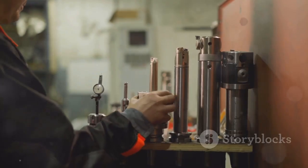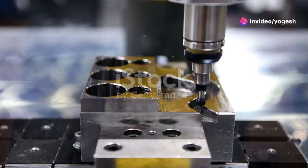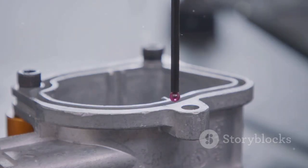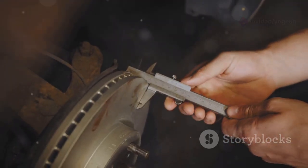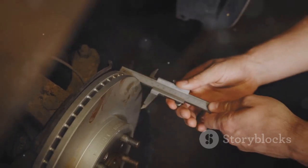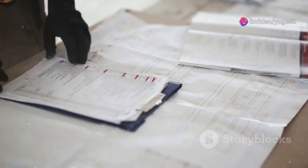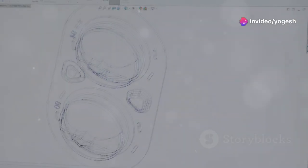Once a part with a spline is made, how do we check it's right? Not with a ruler. Quality control uses tools like coordinate measuring machines, or CMMs. A CMM touches the part at many points, recording their coordinates. Software compares these points to the original CAD model, showing any deviations. Even tiny errors, thousandths of an inch, can be detected. For quick checks, inspectors might use profile gauges, templates cut to the spline shape. These aren't as precise as CMMs, but they quickly spot big errors. Inspection ensures the part matches the design, every curve accounted for.